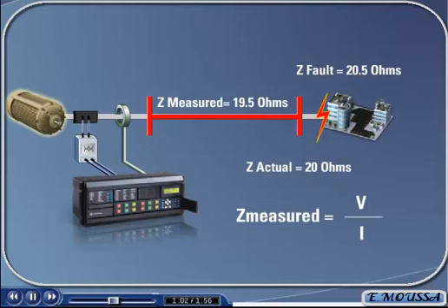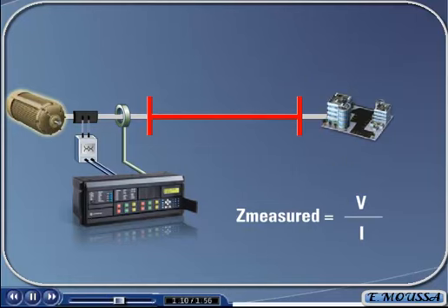This would cause the relay to trip the circuit breaker and shut down this transmission line when it did not need to. Because of these inaccuracies, distance zones of protection are not set to stop right at the boundary of a transmission line. Distance relays use multiple zones of protection, with some of them set short to only protect part of a transmission line, and others set longer to protect the entire length of a transmission line, plus some of the next adjacent line.